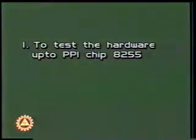Now we integrate the system hardware and software and test it in accordance with its technical specifications. We debug the system for its failures, if any. To do so, we define 3 stages for the debug and test procedures. In the first step, we test the system up to PPI chip 8255 in input and output mode.